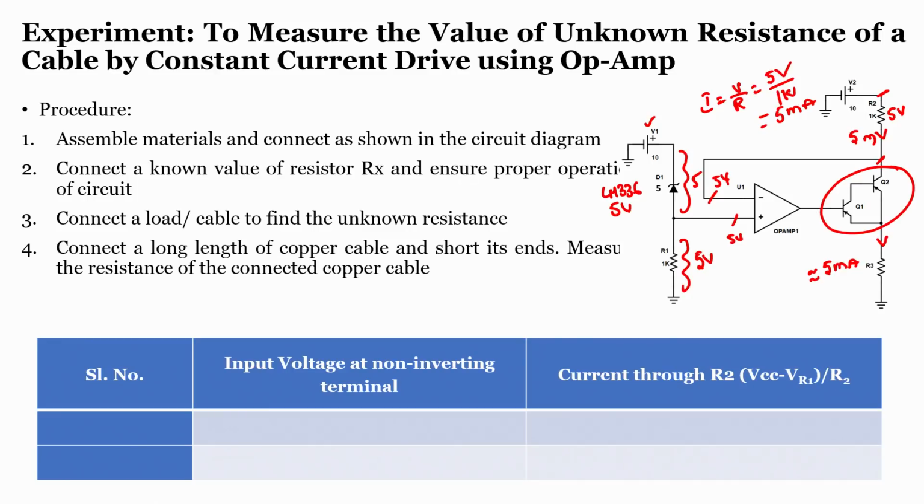So, since our intention was to find out the unknown resistance value, I can measure the voltage across this R3 resistance, and by looking into the voltage and the current, right. So, voltage and the current will give us the resistance value, right.